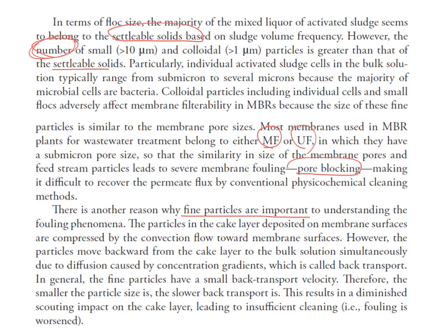The particles in the cake layer are compressed by the convective flow, and these particles cannot be easily removed by back transport. If the particle size is smaller, the back transport velocity is smaller, which means they cannot be easily removed by flow motion near the membrane surface.